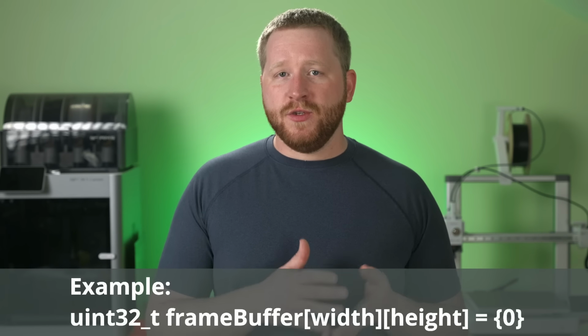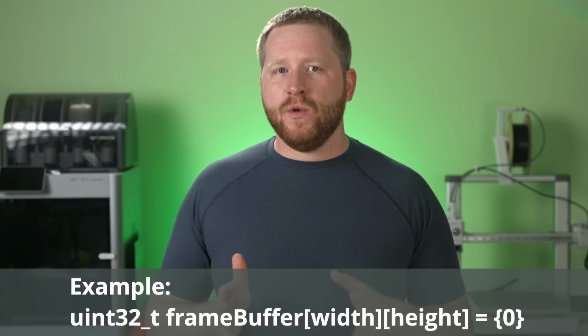We know that a graphical display is merely an array of pixels, each one independently controlled. So it's obvious that we need some way to keep track of what each pixel should be. This is most commonly done with a frame buffer. A frame buffer is simply a data array in your code, usually the full size of the display, that holds each pixel's value. The rest of the graphics code modifies the contents of this buffer, drawing shapes or characters, for instance. When it is time to update the display, the buffer's contents are sent over the communication bus to the display controller. There are many variations of the frame buffer.